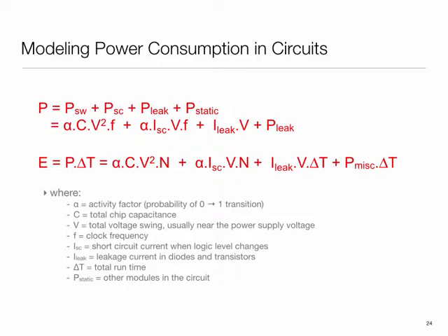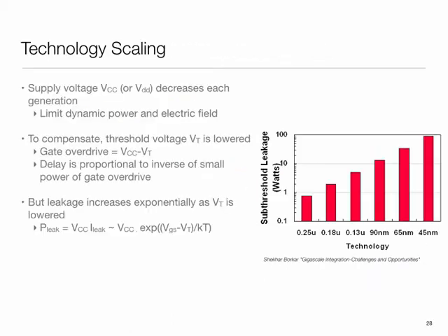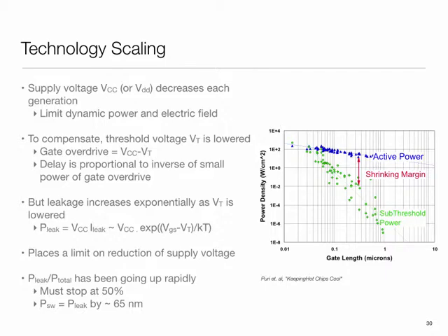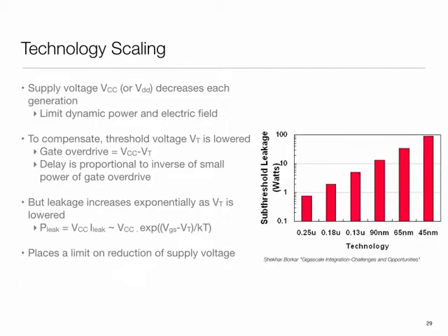So what will happen in that kind of system is that it's essentially a no-win thing, in the sense if you lower the frequency, you are just hurting yourself. Okay. So do you think there is still any benefit to lower the frequency? So as we discussed, from an energy perspective, it's a no-win. You can only lose, right? That dynamic energy contribution remains constant. Energy contribution of leakage goes up.